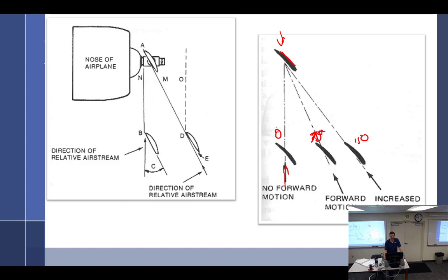I'm getting why those engines have a placard about more efficient RPMs. So this is, again, a fixed pitch propeller. They're not efficient except for one narrow band of where they operate. If it's perfect, they say, oh man, this prop is designed to run at 2,400 RPM. You're like, great, but you also have to go 110 knots.